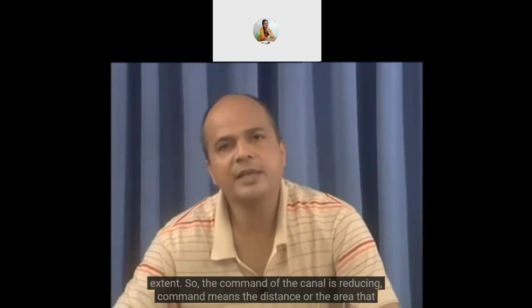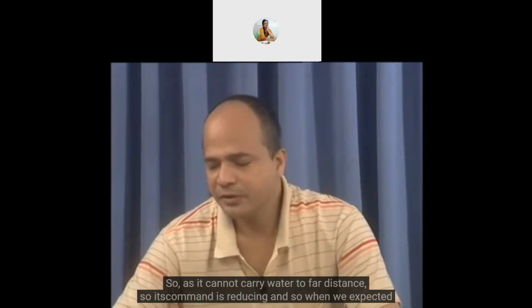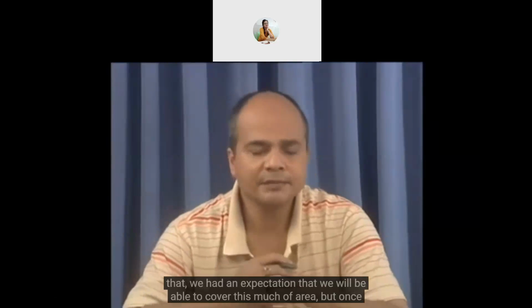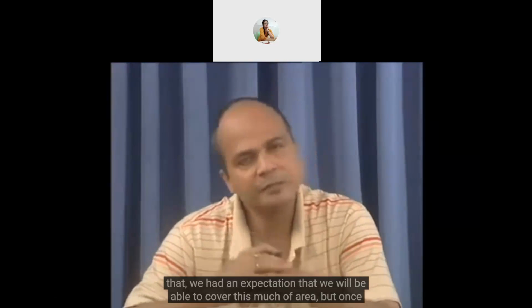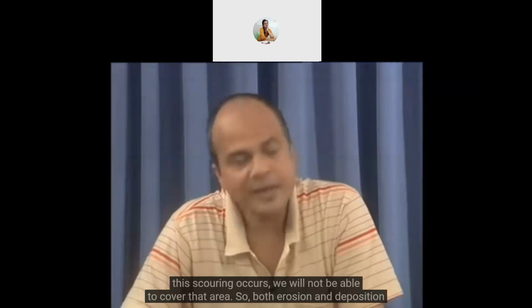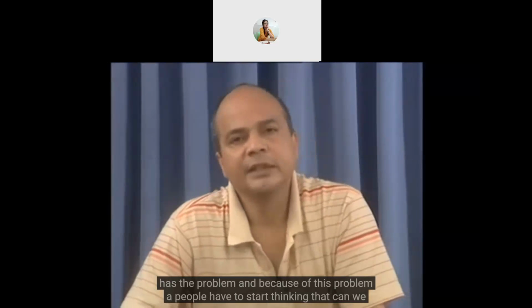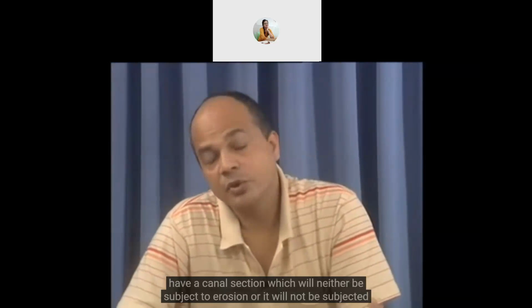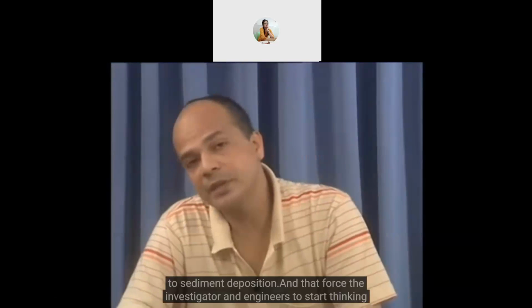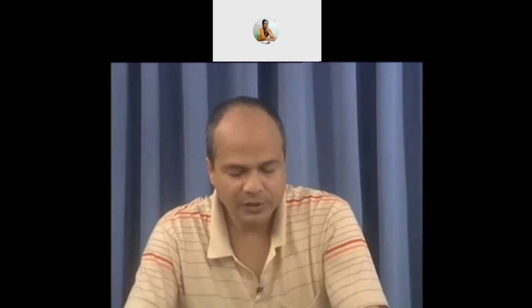Command means the distance or the area that can be covered by a particular canal; it is called the command area of the canal. As it cannot carry water to far distances, its command is reducing. We had an expectation that we would be able to cover this much area, but once this scouring occurs, we will not be able to cover that area. So both erosion and deposition are a problem. Because of this, people had to start thinking: can we have a channel section which will neither be subjected to erosion nor to sediment deposition? That forced investigators and engineers to start thinking along this line.